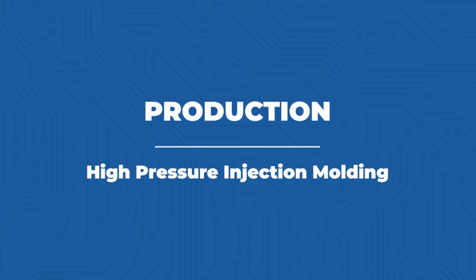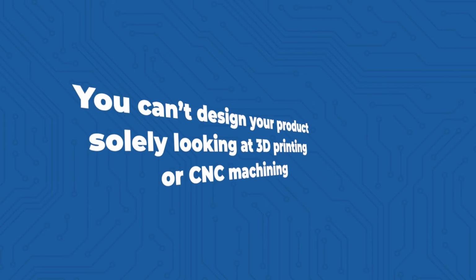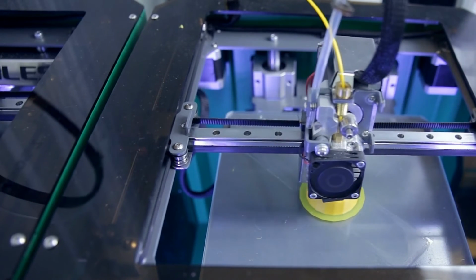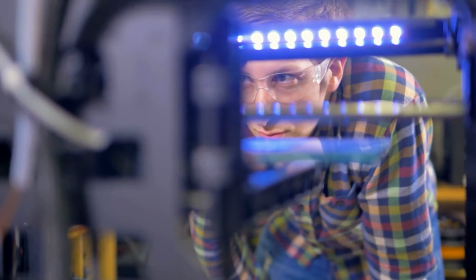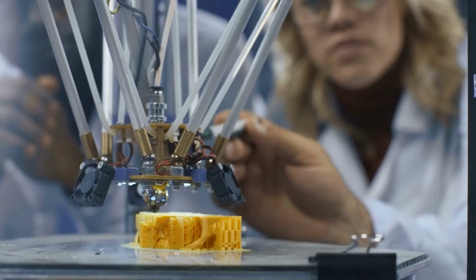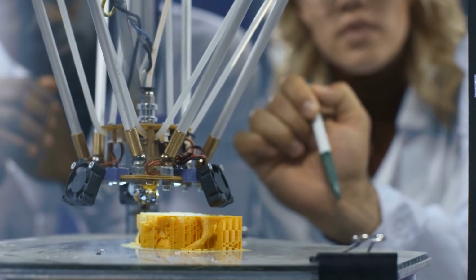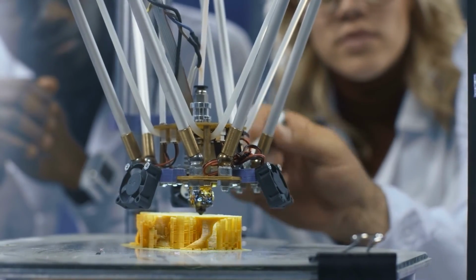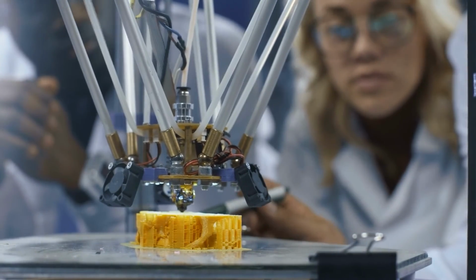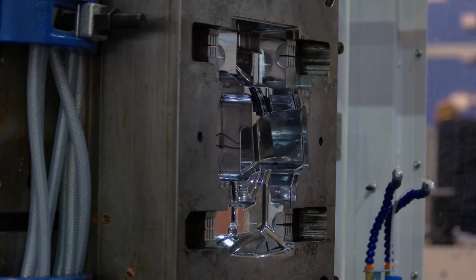But the thing to keep in mind is you cannot design your product solely looking at 3D printing or CNC machining, because what you can 3D print is totally different than what you can injection mold. First of all, 3D printing is not very restrictive at all. You can design a 3D model and have very elaborate parts 3D printed, but you can never actually manufacture those parts using high pressure injection molding.